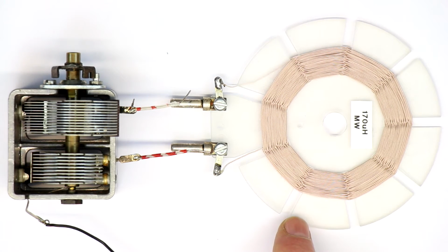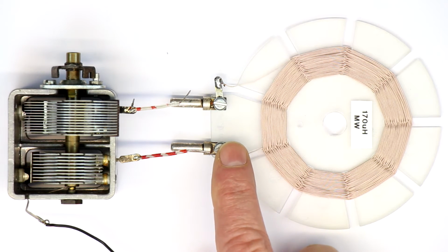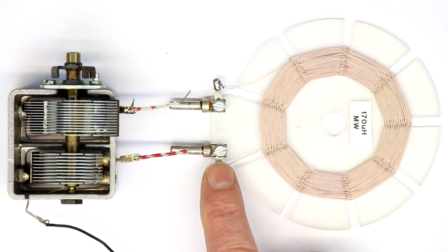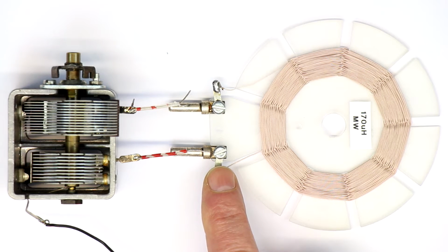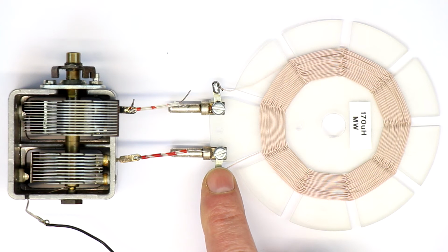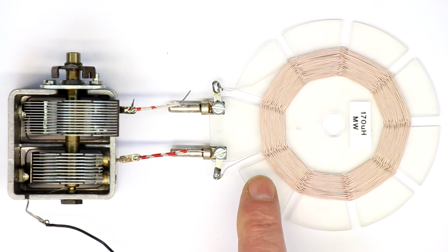And we made some simulations and came to the conclusion, well, the DC resistance is of course important, but it cannot be all, because the calculated and simulated Q factor we got when we only take the ohmic resistance, the DC resistance of this example coil into effect, which is around 2.2 ohms, then we get a much higher Q factor than the real coil has when it is measured.